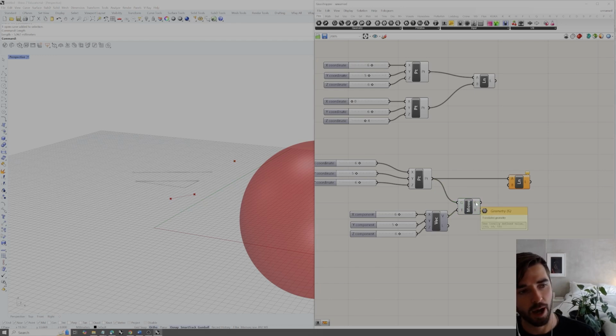If we plug the output geometry, which it says here is the translated or moved geometry, into our B, then we'll have a point that is moved in space to construct that line. So we basically have one original point and a moved point, which are now feeding into a line to construct that line parametrically. And we can adjust this vector value to move this point in space.